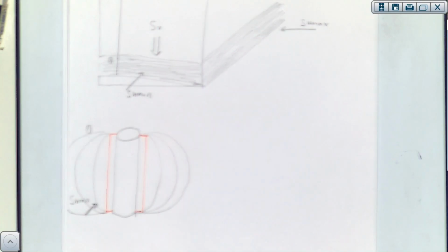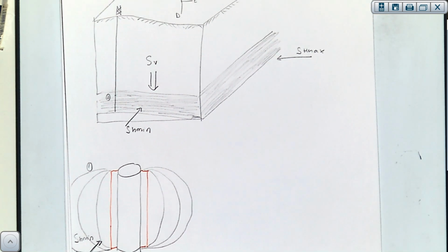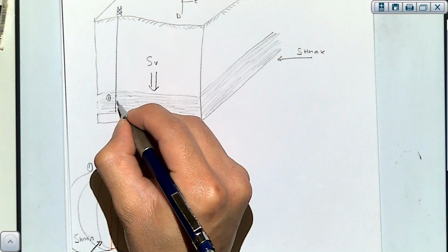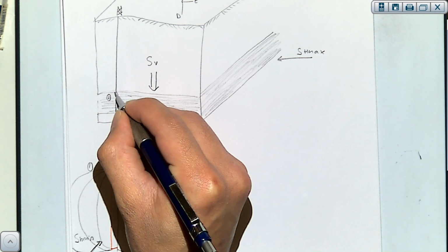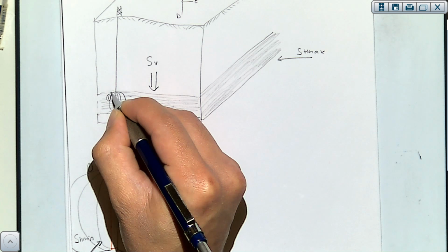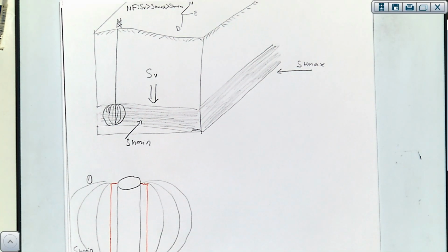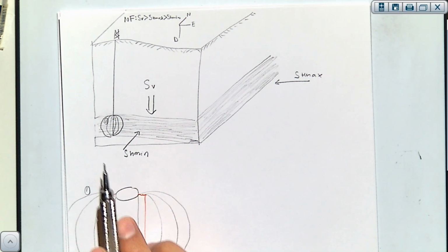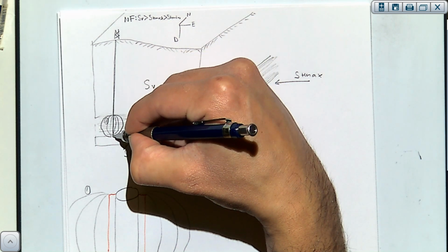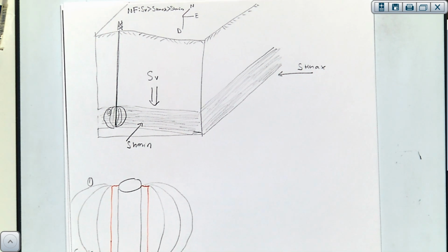And if we put this into our formation over here, that means that if you start a fracture somewhere over here, it will just keep on growing on the same plane perpendicular to SH min. So in this case, if this is a vertical wellbore and you pressurize an open hole completion, that's what you would expect as a hydraulic fracture.